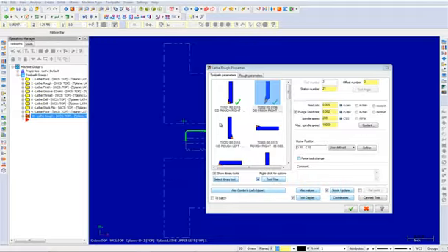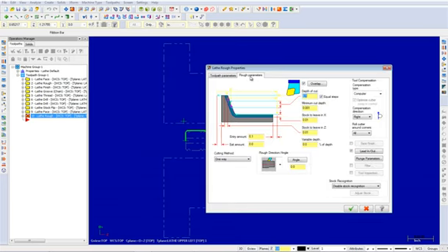Select the OD Rough Right 80-degree tool and input the comment Rough the OD. Next, select the Rough Parameters tab and ensure that your parameters appear as shown. Ensure you set the stock recognition to Use Stock for Outer Boundary. Then pick the OK button to generate the toolpath.